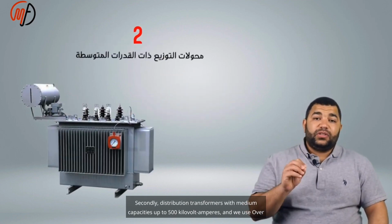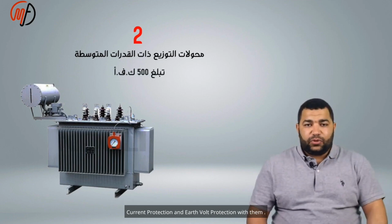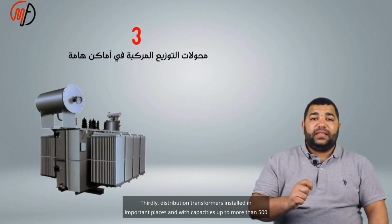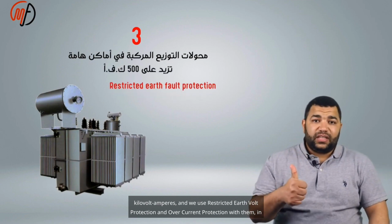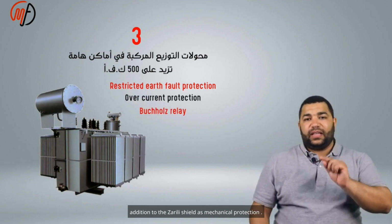Secondly, distribution transformers with medium capacities up to 500 kilovolt amperes, and we use overcurrent protection and earth fault protection with them. Thirdly, distribution transformers installed in important places and with capacities of more than 500 kilovolt amperes, and we use restricted earth fault protection and overcurrent protection with them, in addition to the Buchholz relay as mechanical protection.